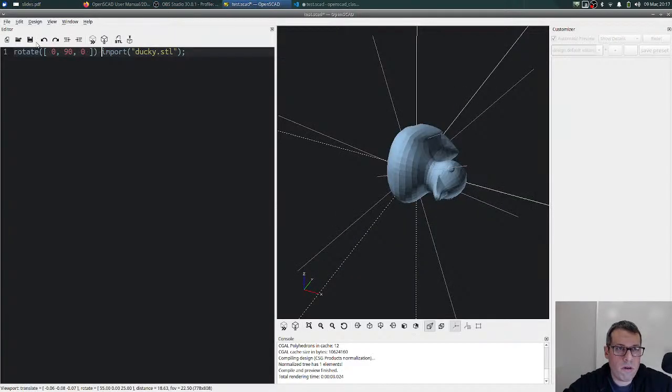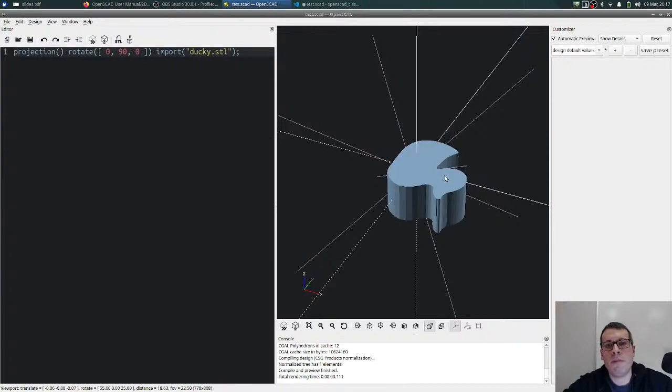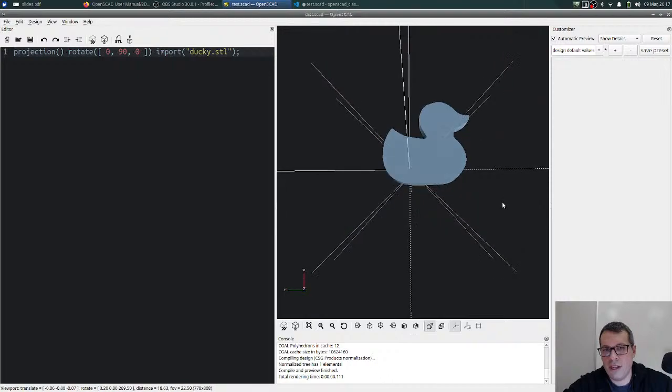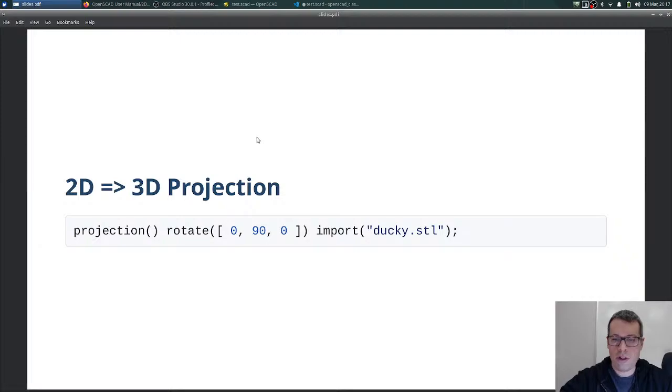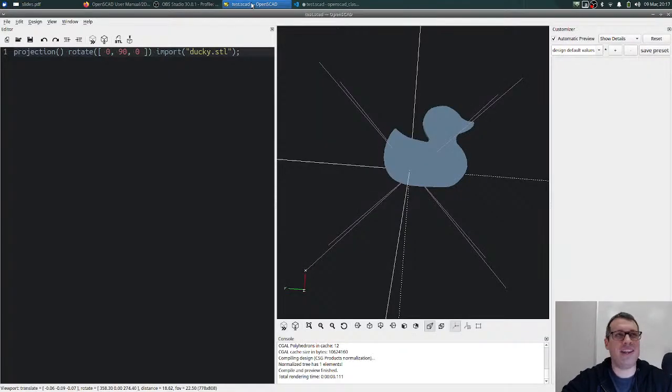projection. So we're going to go here. And so now it's 2-dimensional. It looks 3-dimensional, but I promise you it's 2-dimensional, and we can turn that into a DXF, take it upstairs on a thumb drive, and then cut a hole like that on the laser cutter. So very useful for a very specific type of project. Any questions so far? I know it's really cool, isn't it? I wanna do a bunch of these and have a mallard mesh piece of plexiglass for, I don't know what.